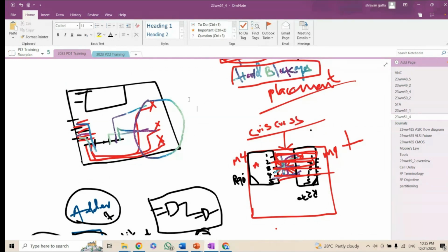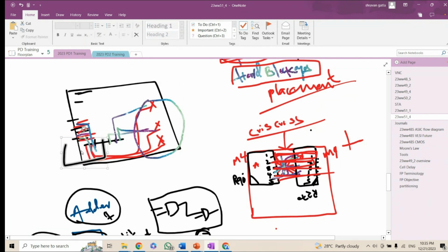If you say yes, one iteration, then you are gone. He will understand that you don't know about macro placement. In real time, no one can finish macro placement at once. Some people do macro placement 100 times, because they place a macro here and here and here, moving it here and there and checking the congestion and timing. And the place where he gets good QoR, meaning good congestion and timing results, he will fix as the placement for that particular macro.